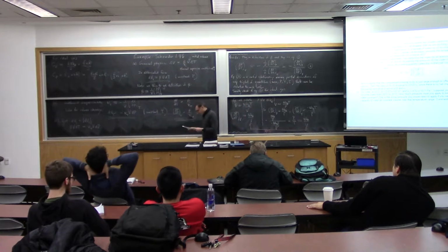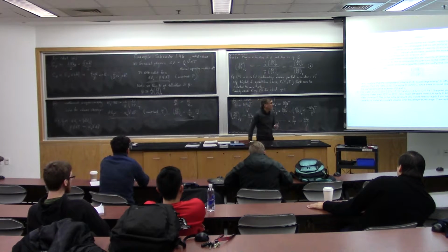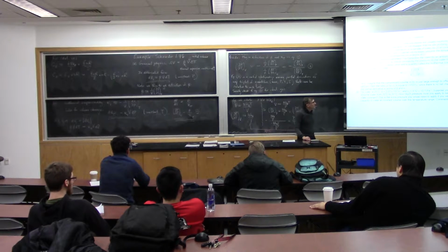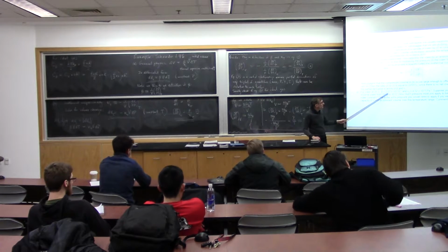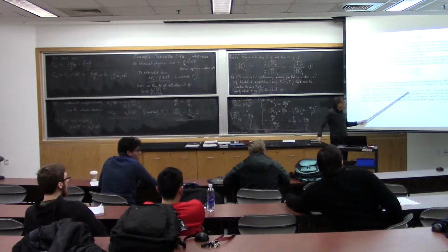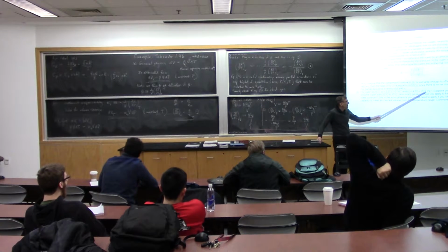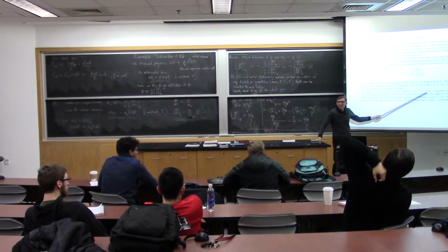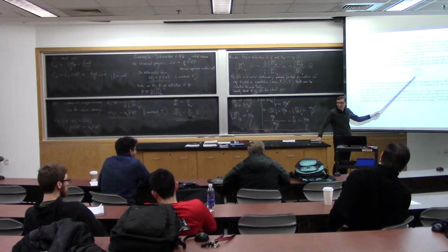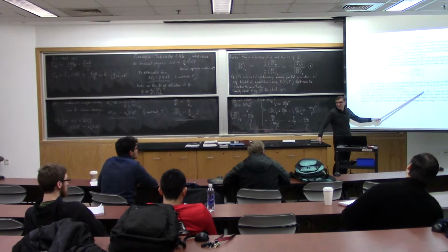All right, now, with that in mind, I have done part C and more. So now let me get back to the example and finish it off with part D. Let's take water at 25 degrees Celsius. The thermal expansion coefficient is 2.57 times 10 to the minus 4 inverse Kelvin. And the isothermal compressibility is indeed a very small number, 4.52 times 10 to the negative 10, and the units are that of inverse pressure. You see how that would come out in the definition? So inverse Pascal. Notice how small that is, just as a number.